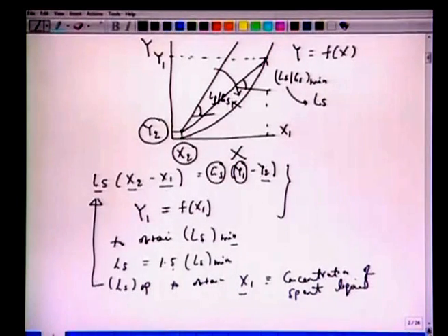So essentially the idea of this small exercise is that we can solve graphically, as well as write down the set of equations: the operating line, which is linear, y equal to mx plus c form, and the equilibrium curve y equal to f(x), thermodynamics. Two unknowns, two equations, we can determine the unknown quantities here. Important to note also that the shape of the equilibrium curve will be different depending upon what type of systems we have, sulfur dioxide, water, ammonia, caustic, etc.